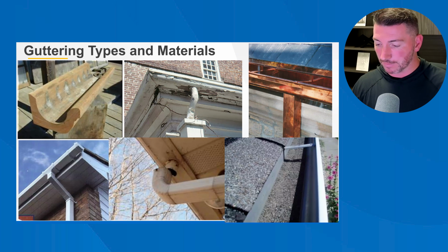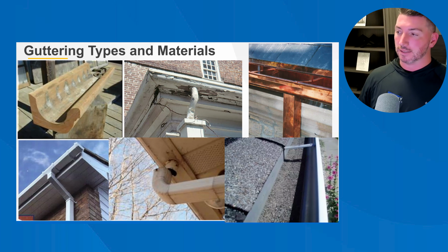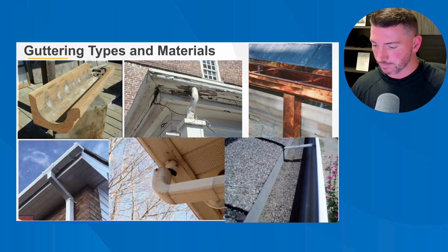Metal and vinyl guttering. The two biggest problems with steel guttering are rust, if not properly maintained, and the potential for leaks in joints and downspout connections. Steel guttering comes in shorter lengths, so there tend to be many joints in the system, not just at the corners. So again, if you're buying steel gutters that are 10-foot runs, they'll be galvanized steel gutters, and you'll usually get rust and holes in the bottom of them. It looks like that center bottom photo is probably steel because I feel like I'm seeing some rust there, but I've been wrong before.